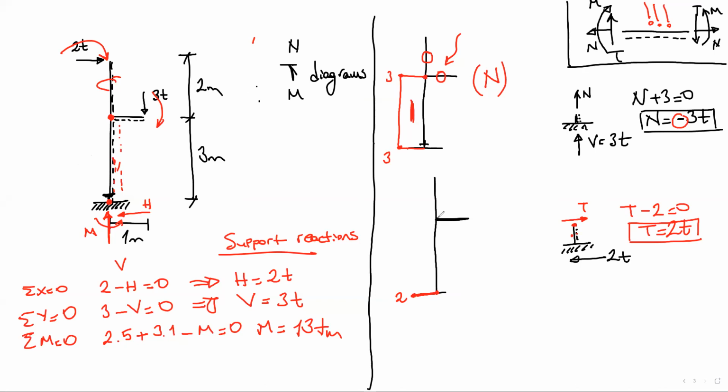When we come to this point, until this point on this vertical column, there is no shear force change. At the top, there is a lateral load which goes right. So if you cut the system and take a look, its sign is going to be positive. So all the way down is 2. Positive or negative?